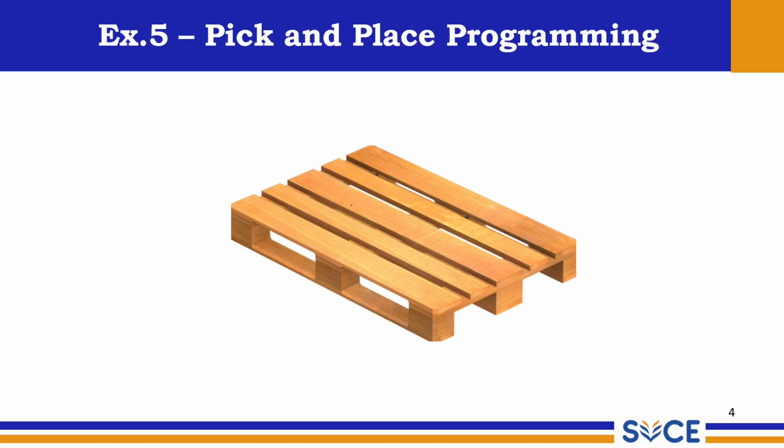It is a small elevated platform. Usually the standard sizes are like this. The length will be 1000 mm, that is 1 meter, by 800 millimeters. This is the Indian standard pallet size. And the height will be 200 mm. You can understand these are all planks of wood. Even though it need not be wood, plastic pallets are also available. Usually 99.9% it will be made out of wood or plastic.